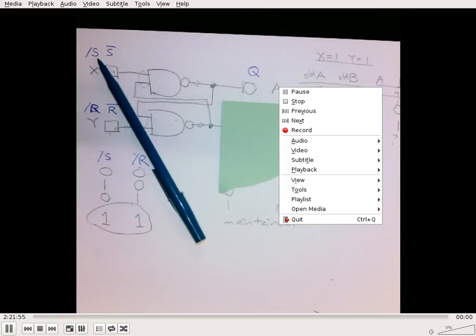So what are these things corresponding to in an actual computer motherboard? One of these may be a reset button, an actual button that you press. Okay, so it's not a transistor, it's an actual button. Change the component so that it becomes an actual button. So you press, you complete the circuit, now you have the connection to the ground. The other ones, one of these is probably coming from what we call a watchdog circuitry.